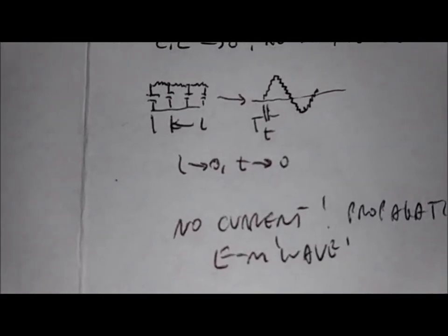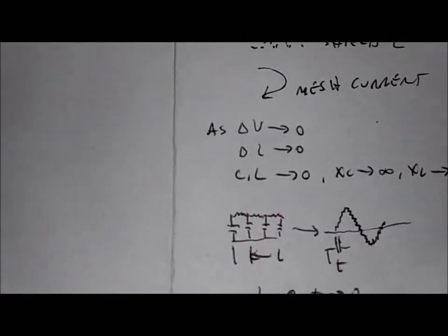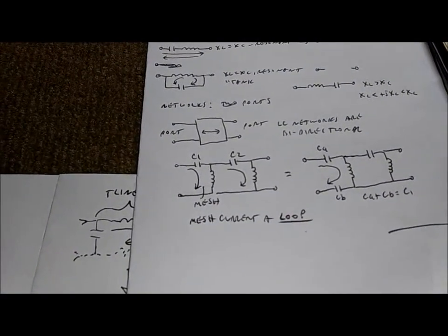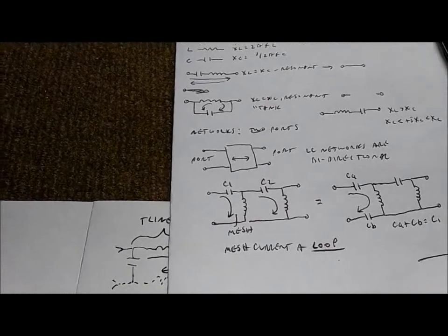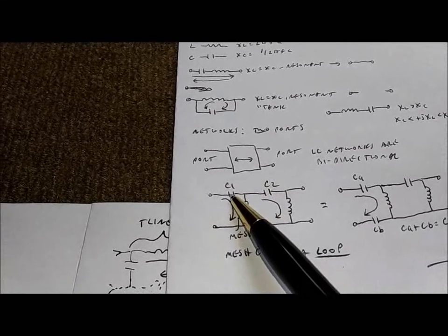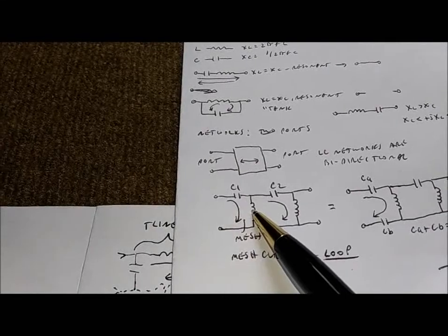No current. This is a horrifying fundamental mistake in antennas and transmission lines, to incorrectly assume that they are discrete elements, as in this previous drawing, and there are currents flowing through them. In an LC circuit there is current, because incrementally a current causes an electrostatic field that goes back to being a current, becomes a magnetic field, goes back to being a current. The going back part doesn't happen in transmission line. It propagates an electromagnetic wave.